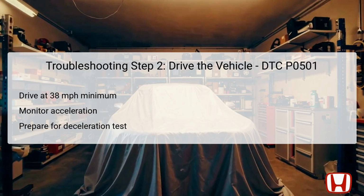After reaching the required speed, ensure the acceleration is steady before proceeding to decelerate. By doing this methodically, the PCM can gather data regarding RPMs and the relationship between them and the speed signal, thereby assisting in diagnosing the P0501 issue.